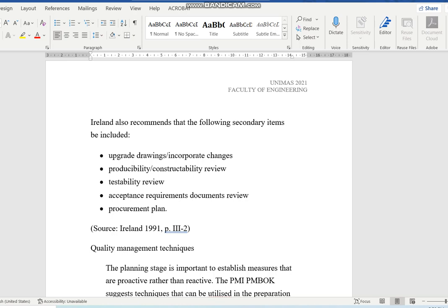what standards, what references are you using, and what sort of local and international standards that you are following, and is it Eurocode, BS code, or which authority standards that you're using. So all this will come into the picture under all the category like methods, material, and manpower. You may have some standards that is associated with that. And then you will also put in drawings, you put in methods, workflow, flow chart, review of the constructability, procurement, and where you buy your products, and then testing, the requirement on testing.